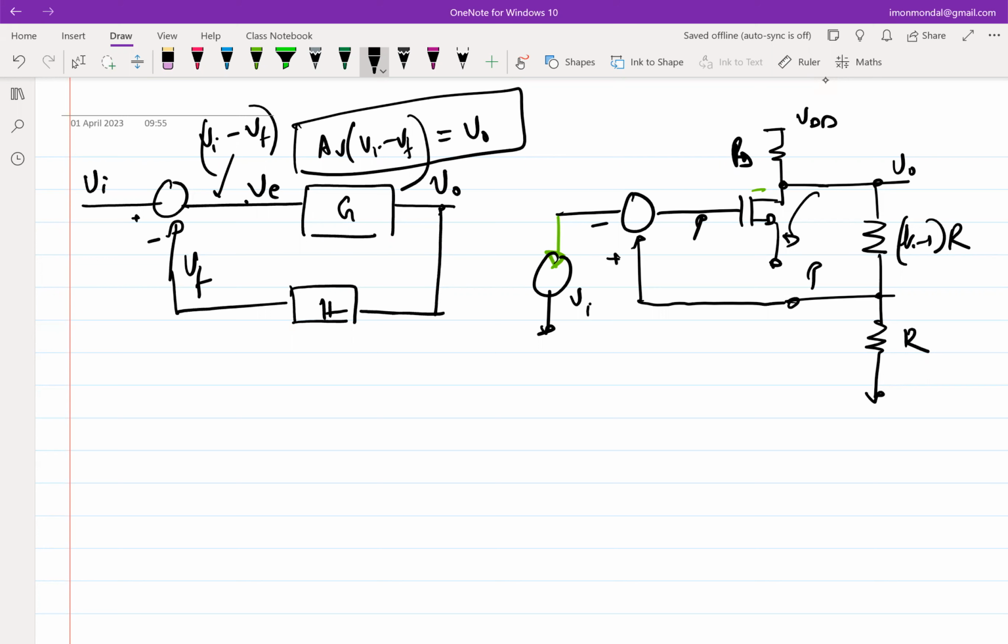Now go to the circuit on the right. What am I saying? I'm saying the gain of the amplifier is infinity by setting gm to be infinity. So what do you think this voltage will be now? It will be 0. It will not get excited. And does it depend on whether I have applied an input or not, or I have applied an input anywhere?